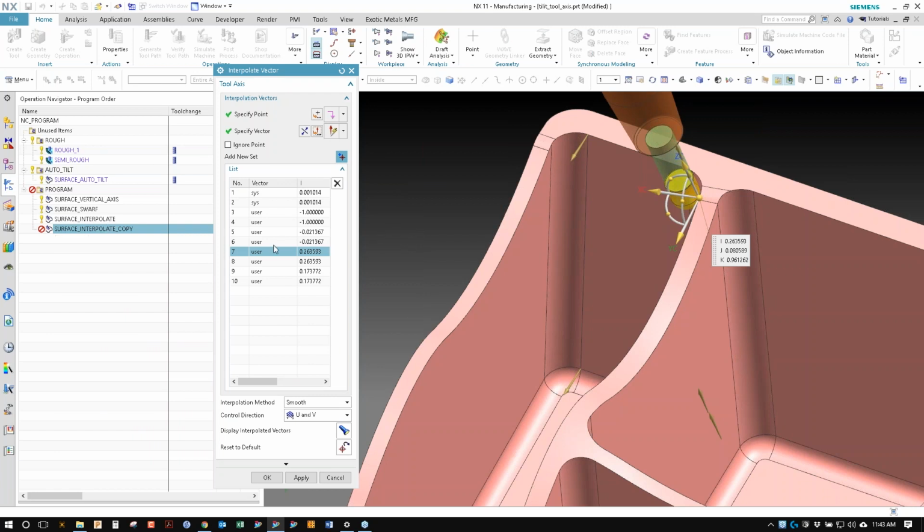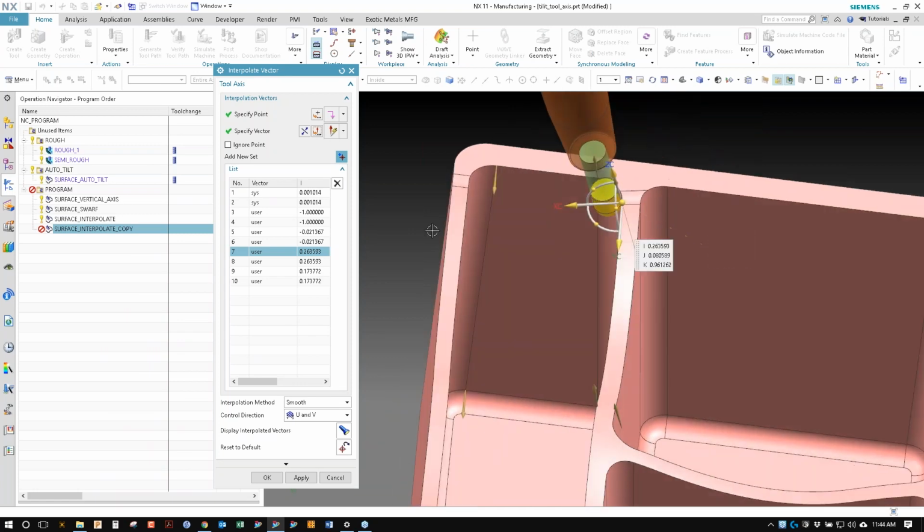So this is one way that customers would resolve this issue where we're getting swing in the corner and having collisions. But setting this, I believe, took me maybe 10 minutes to set all the vectors, somewhere between 5 and 10 minutes. And then of course there's defining your toolpath, so that's separate. You'd have to make sure that you have the step down and everything's smooth.